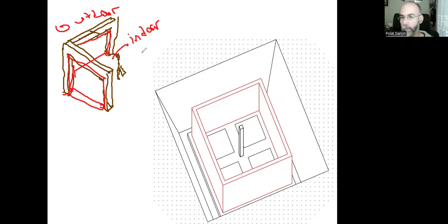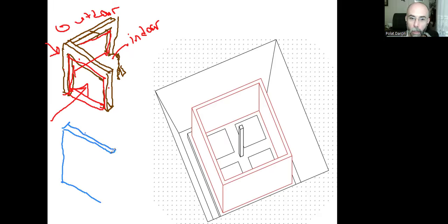However, in the basement floor, because we are going to put all the earth back and there will be pressure of the earth and the water, these walls will not be strong enough to carry all the loads. So instead of this separate column, beam, column frame, we can create just one load-bearing big wall. That will be the shear wall, a big, long column like this.